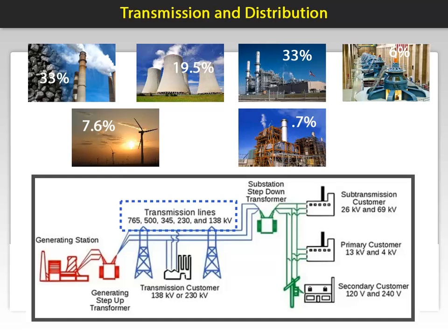Now what is a transmission line? A transmission line is an aerial conductor that carries large amounts of electrical power at high voltages over long distances. You might hear engineers refer to these as high-tension lines. The transmission voltage level is determined by the required transmission distance as well as the amount of power carried. A larger transmission voltage is chosen when dealing with longer distances or larger transmitted power levels. As you can see, these voltages have a wide range.